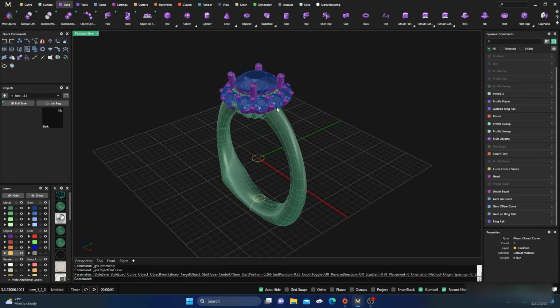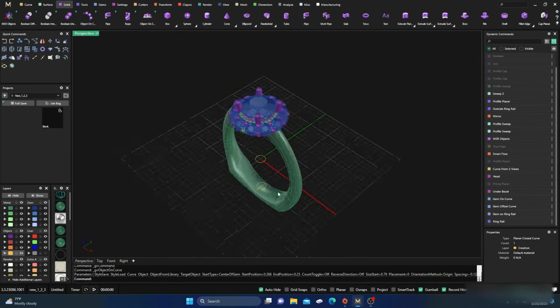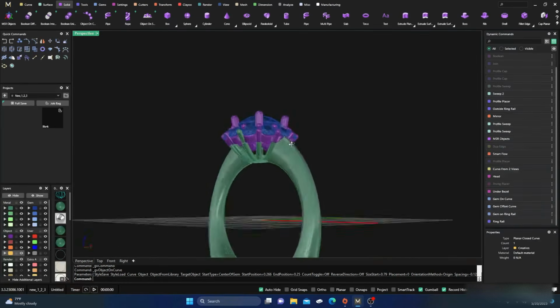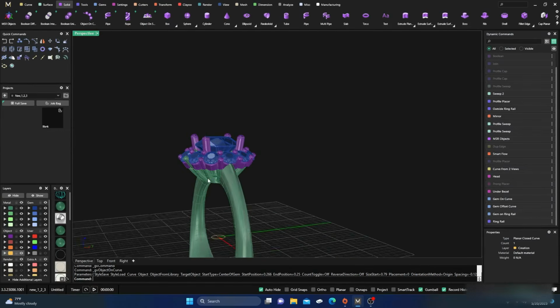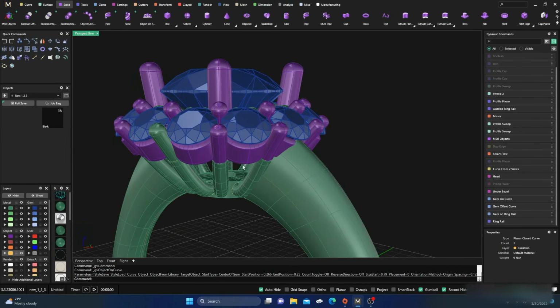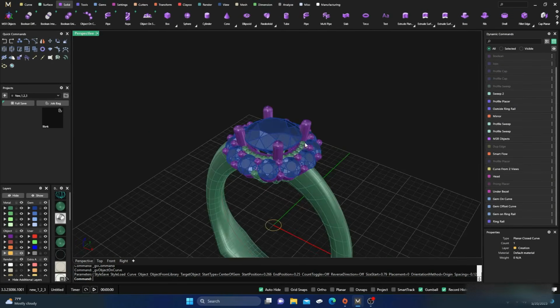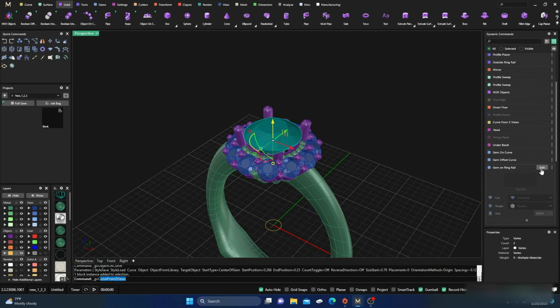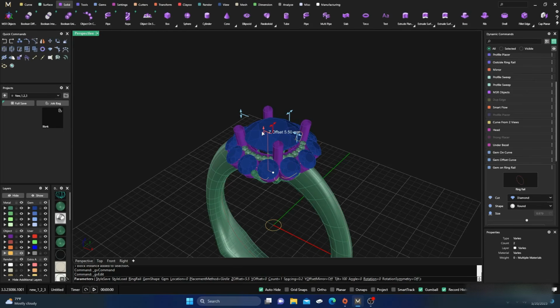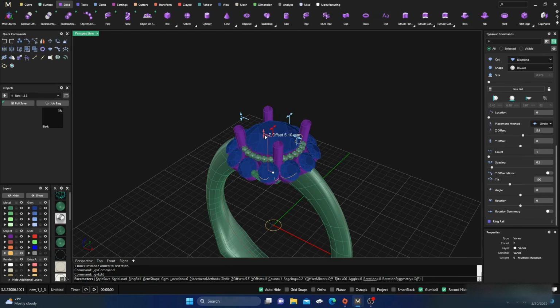So there's a lot of things you can do in here. You can go and change these shanks up. You can do a split shank. You can do a cathedral shank. There's all kinds of it. This is really just a simple way to show how to do this stuff here, and keeping it all parametric, so you're able to go back and manipulate some things, but not everything when we do this. So let's wait for that update here.